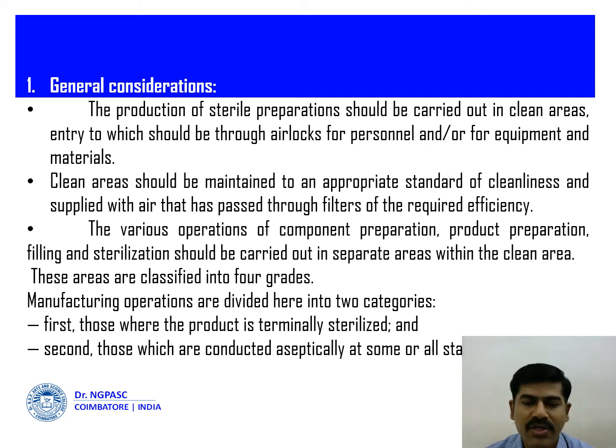The various operations of component preparation, product preparation, filling and sterilization should be carried out in separate areas within the clean areas. These areas are classified into 4 grades. The manufacturing operations are divided here into 2 categories. The first is those where the product is terminally sterilized, and the second is those which are conducted aseptically at some or all stages.